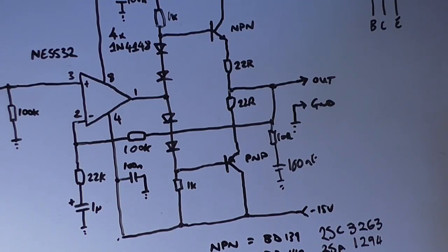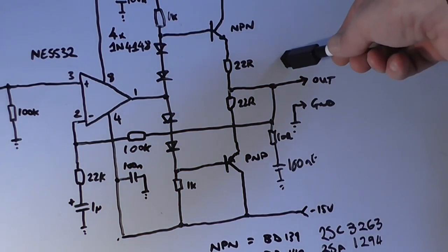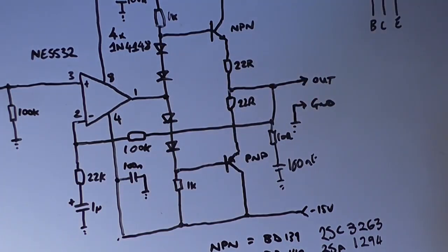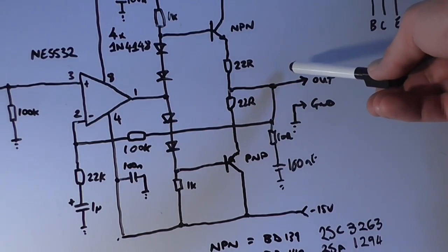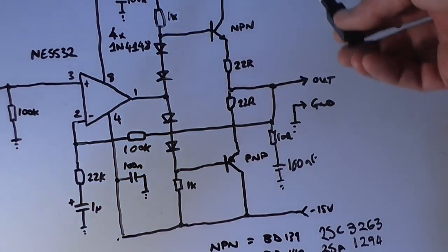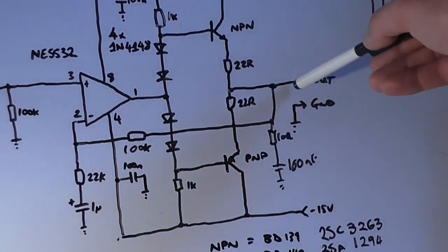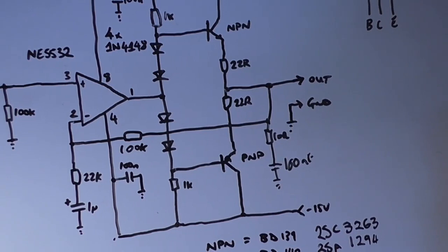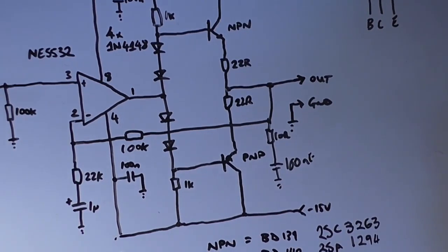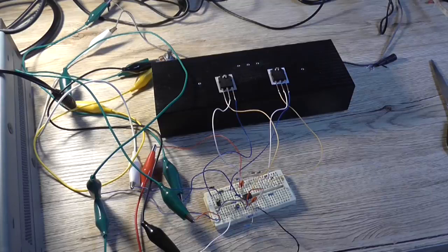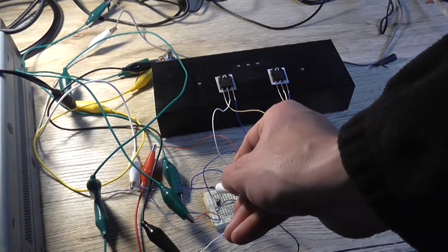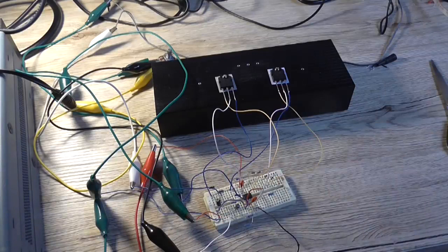But nowadays it's been found really through testing that having the output coil and resistor network there isn't really needed. But it depends. The reason why a lot of amplifiers have a coil like 0.7 microhenry or something like that, and a 10 ohm resistor or a 4.7 ohm resistor in parallel with it, is for driving capacitive loads. But that's the whole entire circuit tested. As I say, those 22 ohm resistors are underrated for the job.